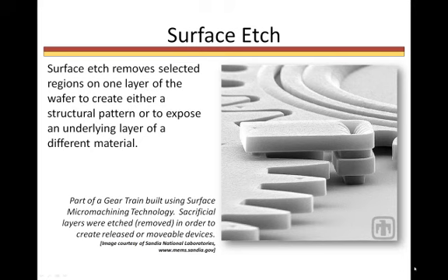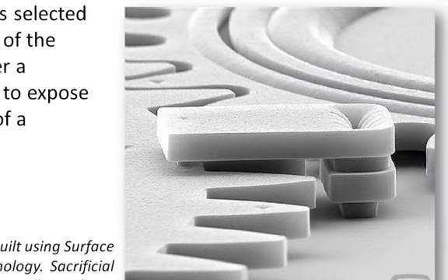For mechanical components, the surface layer is patterned with specific shapes for structural components such as cantilevers, mirrors, or probes. These mechanical elements can be conductive, as in the case of electrodes or cantilevers. The exposed underlying layer can also allow one to anchor a mechanical structure to it.